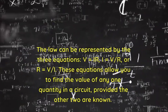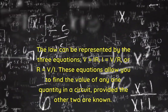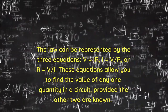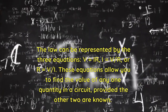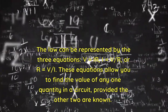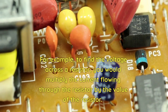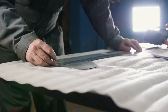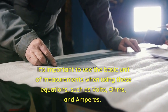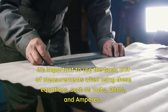The law can be represented by three equations: V equals I times R, I equals V over R, or R equals V over I. These equations allow you to find the value of any one quantity in a circuit, provided the other two are known. For example, to find the voltage across a resistor, you would multiply the current flowing through the resistor by the value of the resistor. It's important to use the basic units of measurement when using these equations, such as volts, ohms, and amperes.